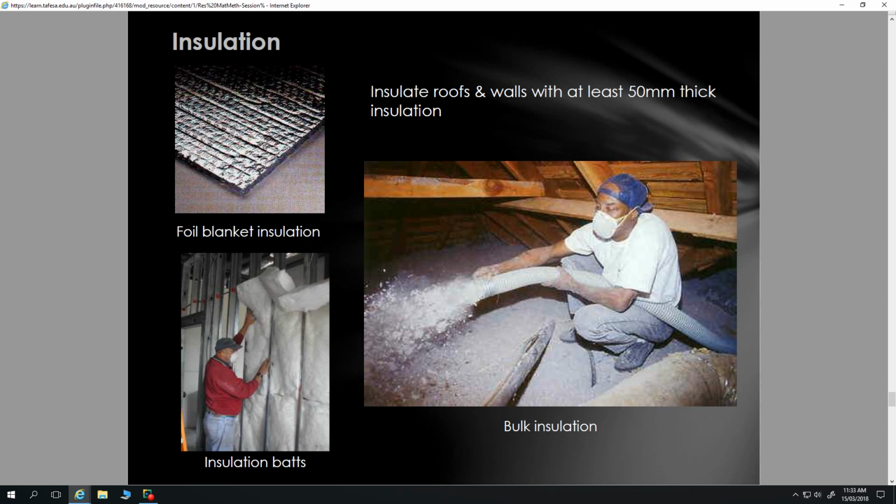I know some people have poo-pooed it. I guess they don't like it for working in the ceiling afterwards. I'm not sure if all that criticism really sticks. I still like the product, because it forms around your ceiling joists really well and locks in there, so you don't have gaps.